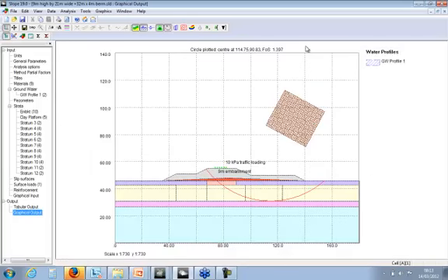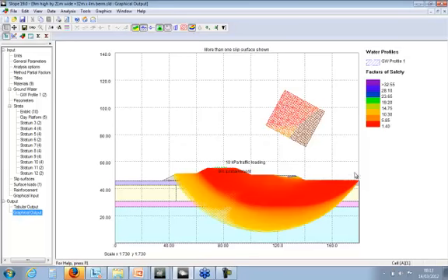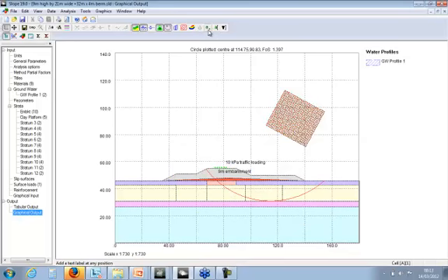So as you can see here, what the analysis has done is it's used this grid, and it's extended the grid in whichever direction it needs to go to choose the worst case factor of safety. So this is hitting 1.4. So as you can see, this embankment is successful in terms of the design parameters. Of interest to people is that you can actually plot a range of circles here, so you can see where your slip circles are going, and where the range of failures are occurring. So that gives you an idea of the problem, and you can also input labels very easily now.